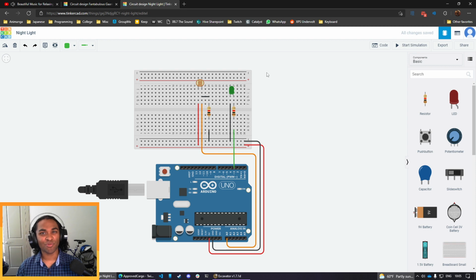Because the current is just a measurement of, I suppose, the speed at which electricity flows, although that's a little bit of a misnomer. But yeah, essentially, what a photoresistor does is it acts similarly to a resistor, except that it doesn't have a static resistance. And so here's where the photo part of the name comes in, right? With a photoresistor, depending on how much light is present in your environment, the resistance of the photoresistor will change. So if there's less light, I believe the resistance will increase, and if there's more light, the resistance will decrease. I believe that is the correct combination there. But anyways, if it wasn't correct, you could just flip-flop your wires and be fine.